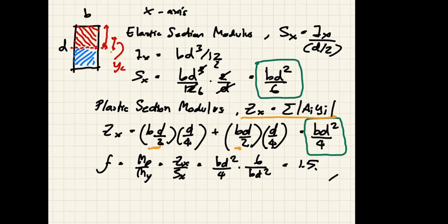But this also gives us the typical formula for the plastic section modulus of a rectangle. So if you find a rectangle that shares the centroid with the plastic neutral axis, you can use this formula right away as well.